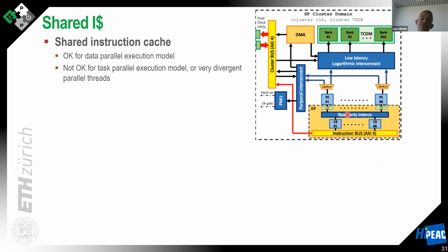The idea here is that you develop a hierarchical instruction level cache that is using only private level 0 cache. That is, a loop buffer that is very small, implemented with latches, and super energy efficient.